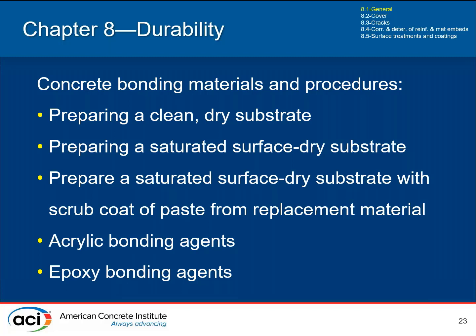They can work really, really well, but they can also work really, really poorly if they're not used correctly. So if you are considering a bonding agent, you should be very aware of what the manufacturer's recommendations are for things like open time and cure time prior to application, and compatibility with different materials before they're used, and make sure that the contractor is aware of them and then using them correctly, so that you have the best chance of achieving a successful repair and a successful bond.